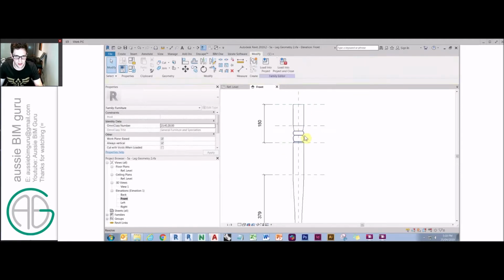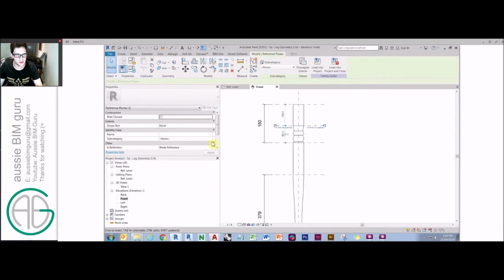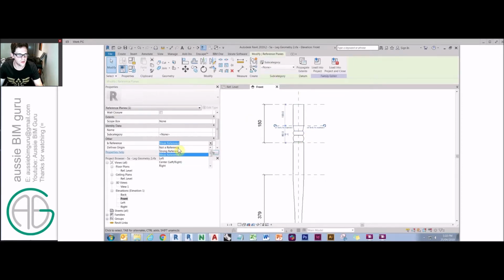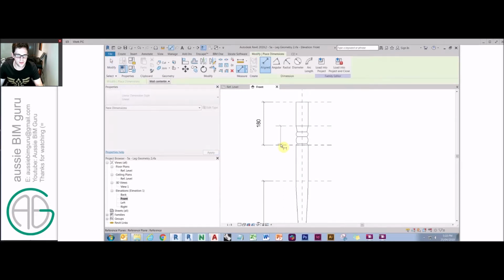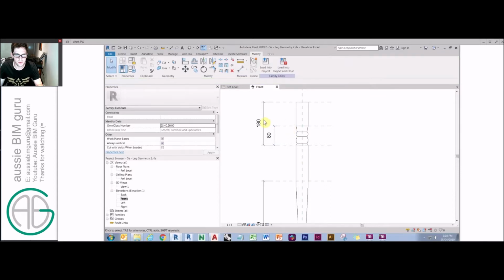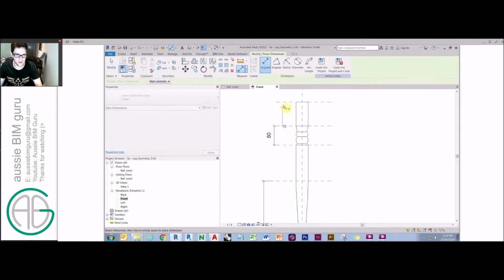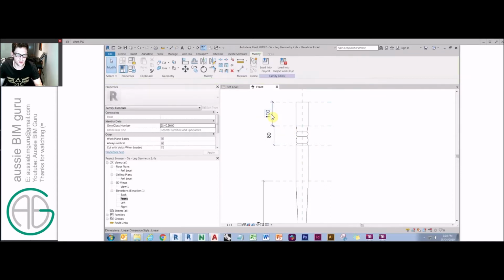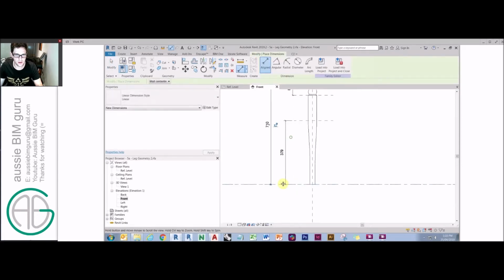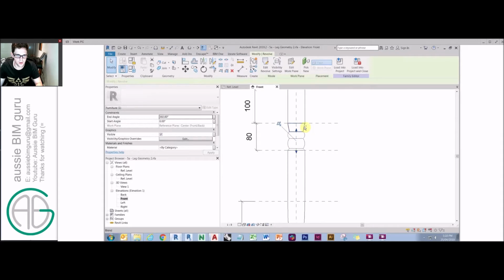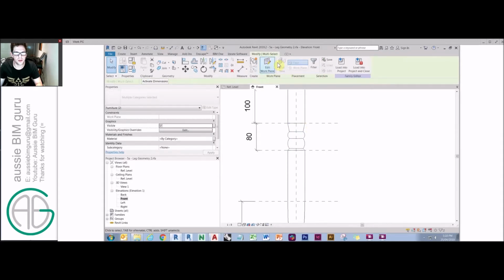So mainly because we have a set of curves here that are struggling to resolve their constraints when they change height. So the easiest way to deal with this is to create the zone that you want to fix elements between. And then we'll create our flexible zone here. Well, not currently flexible, but could be. And this is our flexible height here. And what we'll do instead is we'll group the elements that aren't behaving.